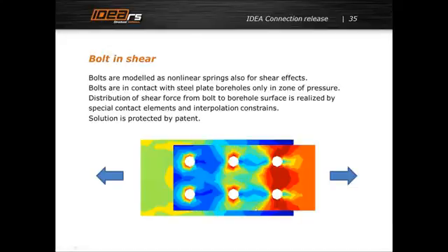So the shear is calculated with this special model with contact elements, and we also do a special mesh around bore holes.